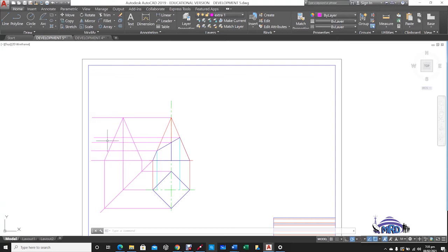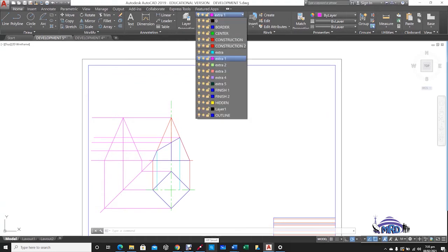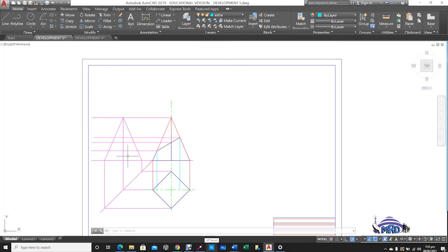So now that we have plotted the center line going on to the end view, we can then proceed to pull that line back on to the plan. So we go back to the lines that we were using before for plotting that component, and we bring these now down to 45 and back on to the vertical center line of the plan, and that will allow us to show the points that we'll need in the plan view.